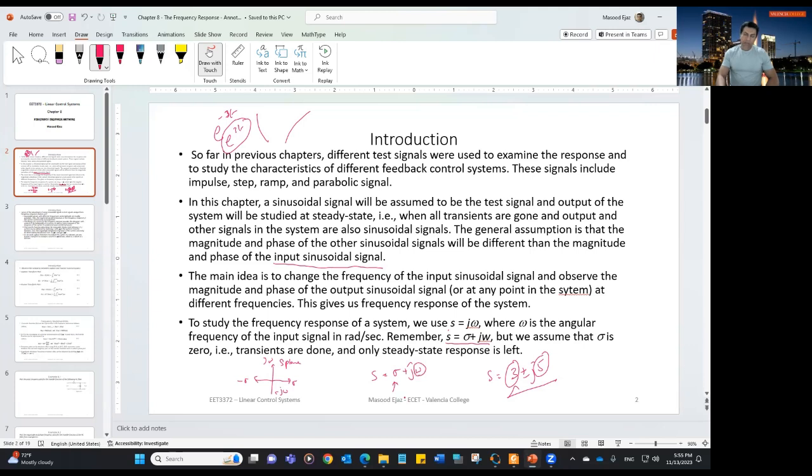what does this frequency do, like how is the signal going to use this frequency? I don't know if that makes sense or not. How is the signal going to use this frequency? Where is it represented in the signal that you're going to get in time domain? Because 3t or negative 3t represents damping, exponential decay or exponential increase of the signal. Now that frequency, angular frequency, you're right, it is an angular frequency, 5 radians per second. This frequency corresponds to what part of the signal? Which part has this frequency?